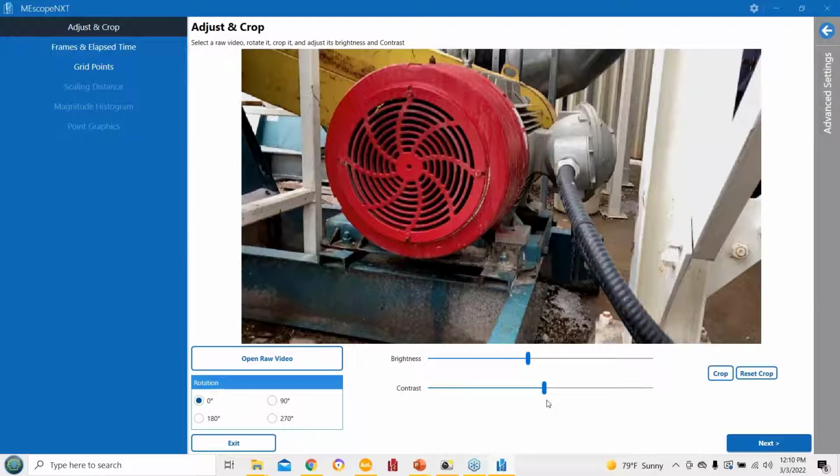So you're losing a little bit of the high speed part of it. Like you can go 500 frames per second. This is 240 frames per second, but in that frequency range is about 90% of faults that are phase related that we can actually see, instead of things that aren't making enough vibration or don't go into a pattern. So an ODS shape is extended into the video range, and we can process it and look at it. And once we rescale all the pixels.